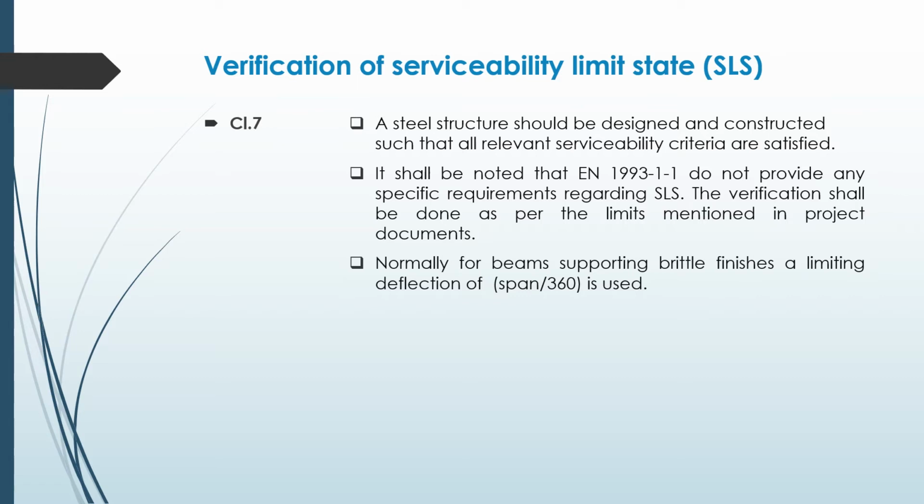Having verified the capacity requirements for the bending and shear force, we need to finally perform the verification concerning the serviceability limit state, SLS. As per clause 7 of EN 1993-1-1, a steel structure should be designed and constructed such that all relevant serviceability criteria are satisfied.